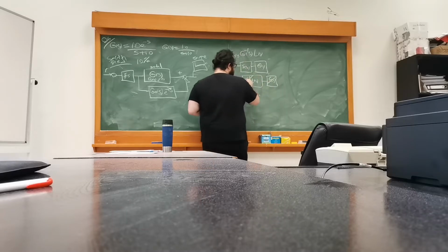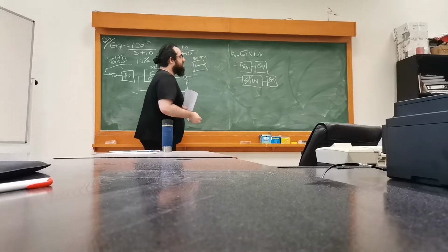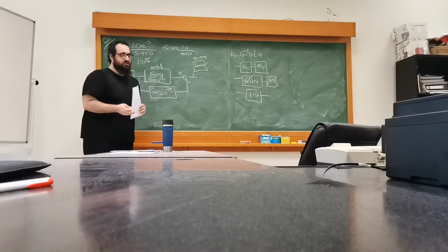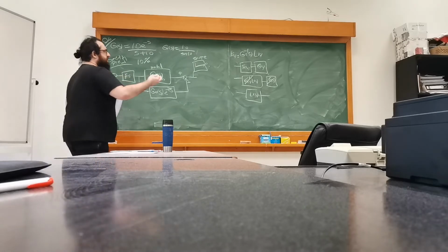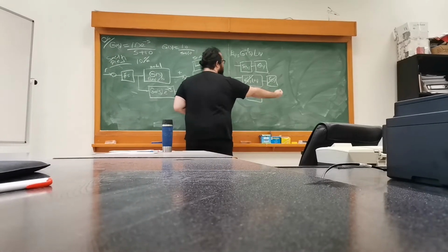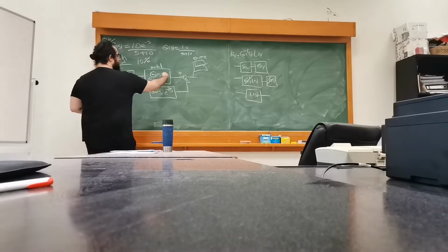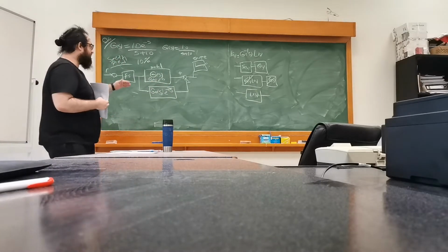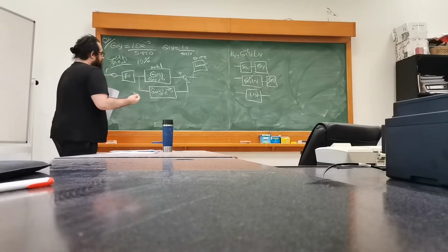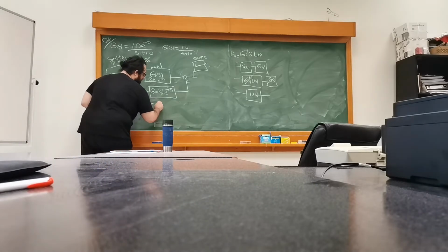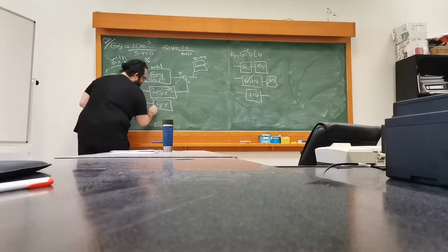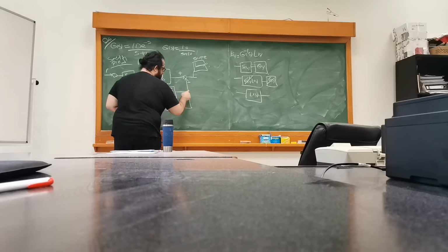And you can see that these portions cancel each other out, and we are left with L(s), basically. So this was the aim of the model matching controller. And here, instead of having this multiplicative cancellation, we have this additive cancellation, basically. It's the same mentality. We're canceling out the model. But, of course, not exactly, because we'll add the minimum phase part to the system back.